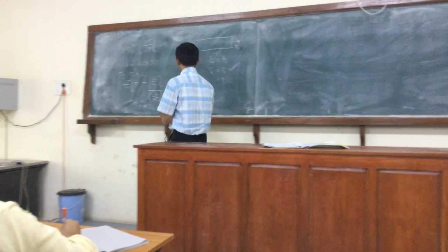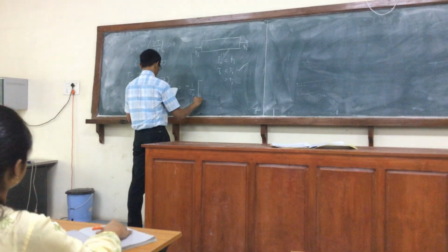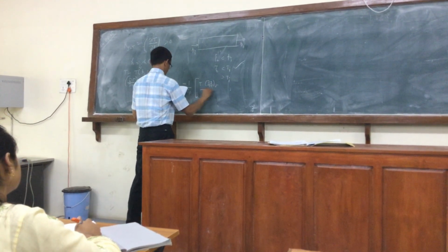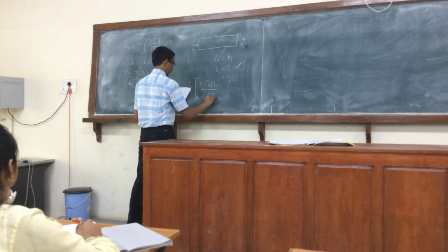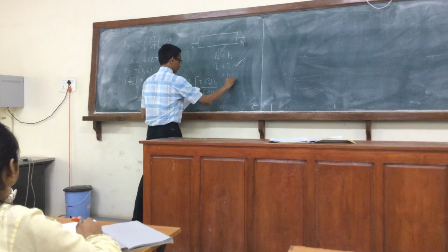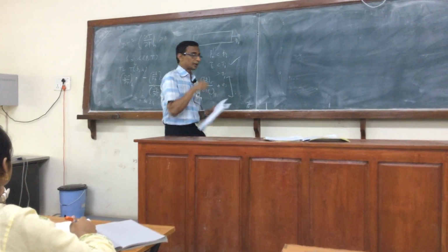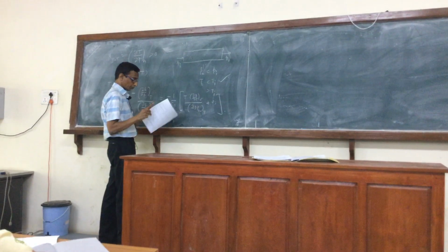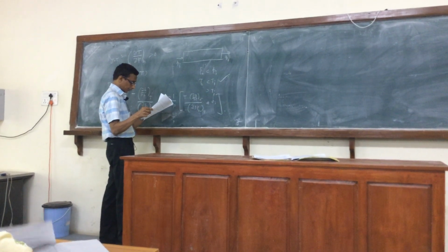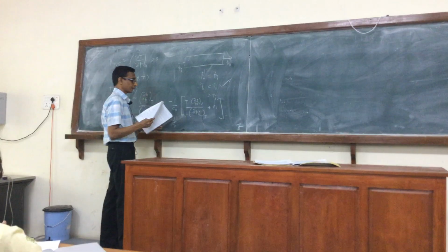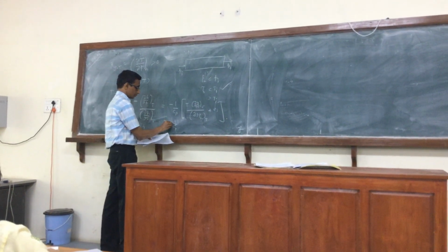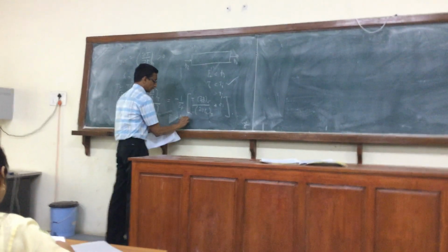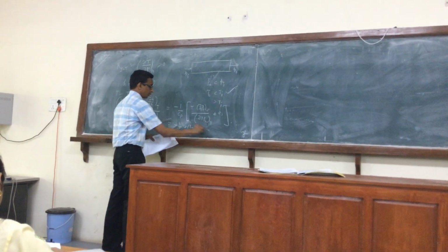So this is dT by dP at H, which can also be written as minus 1 over Cp. If you look at the other set of formulas that are given in terms of beta and kappa, you can write this as V times 1 minus T beta.